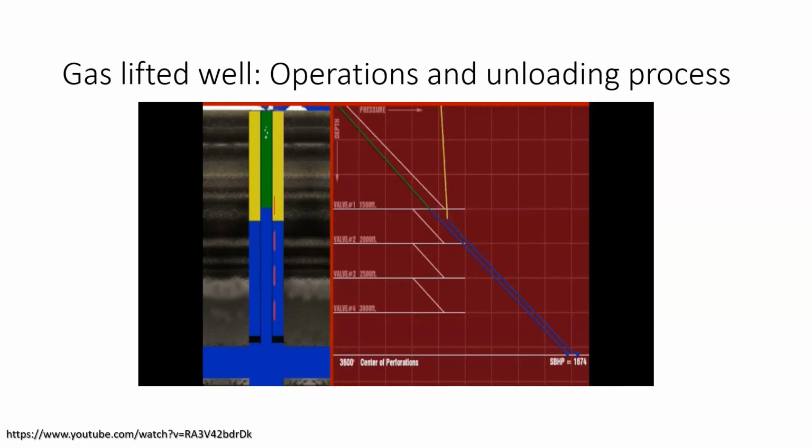Once the annular fluid is displaced to the second valve depth, injection gas begins entering the tubing from the second valve. The combined injection of the first and second valves exceeds the throughput of the surface input choke, resulting in a casing pressure decline. This decline causes the top valve to close.